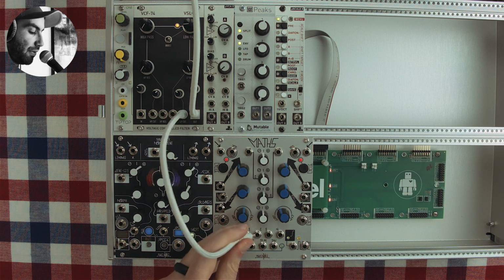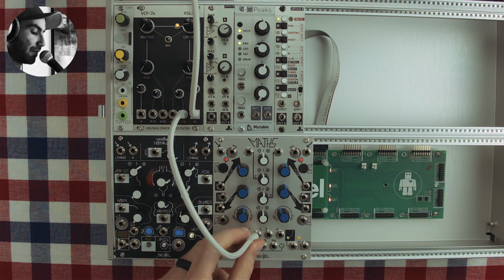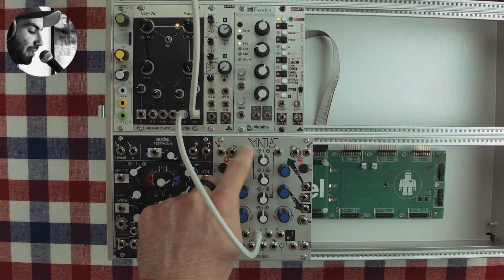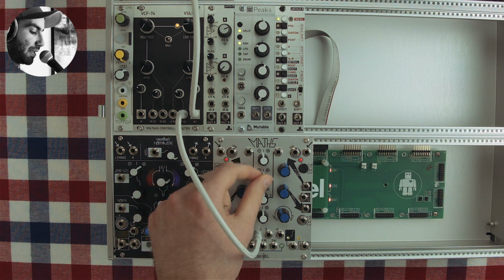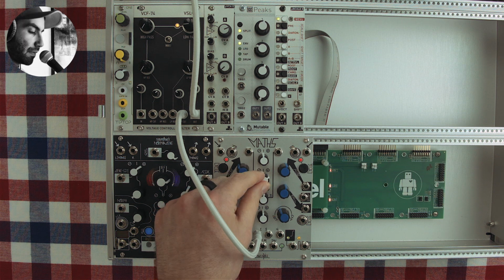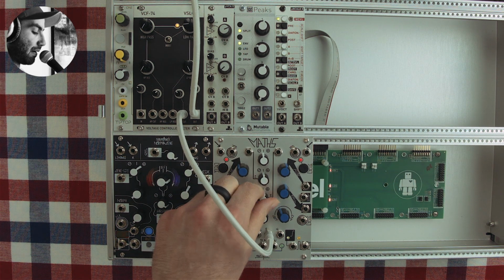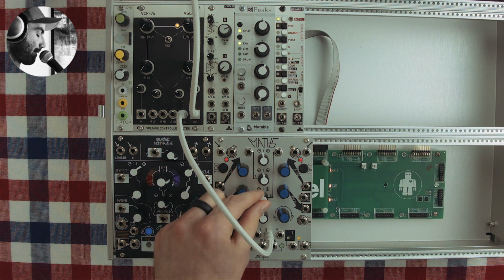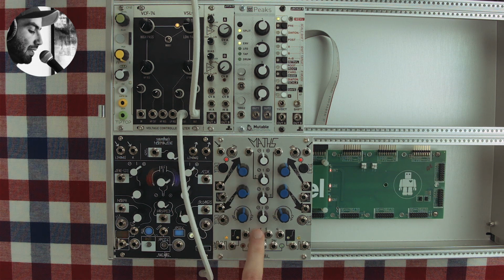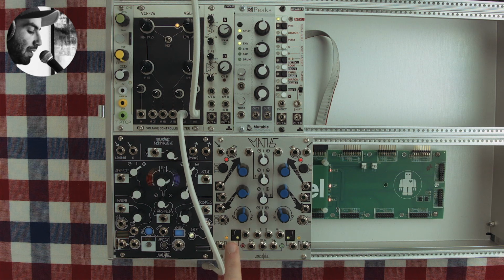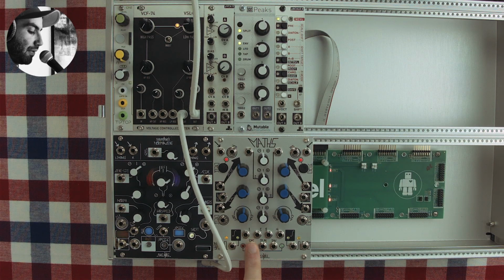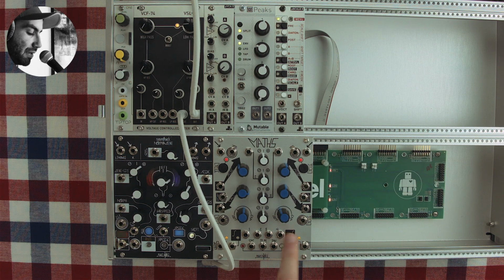And if you remember, channel 2 and 3 are normal to 10 and 5 volts DC respectively. So with nothing patched in here, I basically have up to a 10 volt signal I can patch out. So you just get a direct control of the signal. And similarly for 3, it goes from 0 to 5. And that's basically it. So these output the individual channels attenuated. These here output 1 and 4 without attenuation. And then down here you have the 3 different equations that are different combinations of these weighted inputs.